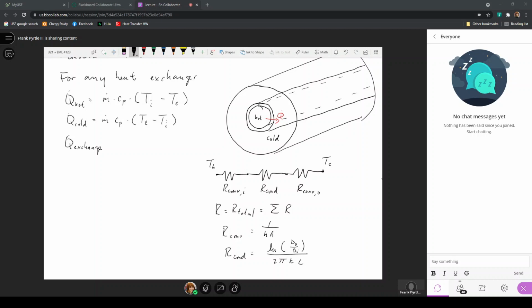So as we move along the length of this heat exchanger, the resistances due to convection will be changing. And so this gives us reason to define another expression, or actually redefine another expression that was first presented in chapter 3, called an overall heat transfer coefficient, where the overall heat transfer coefficient, U, is used to define a combination of thermal resistances, or is based on a definition of multiple thermal resistances that have an overall heat